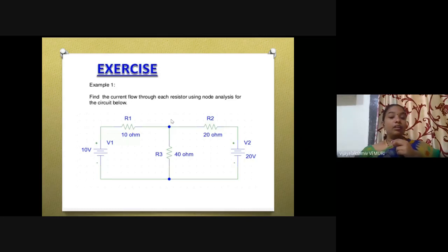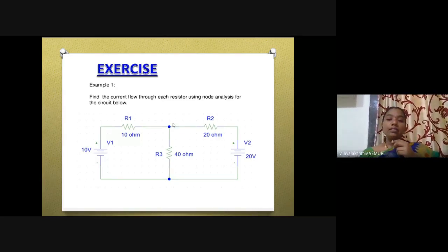Mind you that the nodal method is applied to junctions. Generally we don't call it junction analysis, we call it nodal analysis because we are applying KCL to essential nodes. Now observe from here to here, only one branch is connected. Next, coming to this one, again the current flowing through these two is the same, so both are considered to be an essential branch.